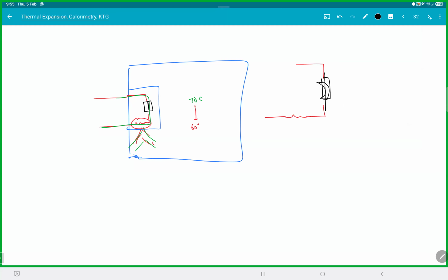So you can maintain a certain temperature range in the room, maybe between 50 to 70 degrees, without anyone coming and operating, it automatically goes on. They still use these things in fire alarms. So when the temperature rises in the room, the bimetallic strip bends, and there is a small liquid there, it breaks, and then the fire alarm rings and all that.